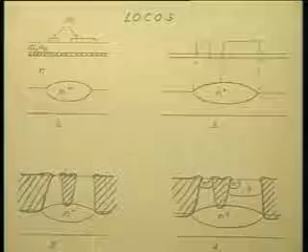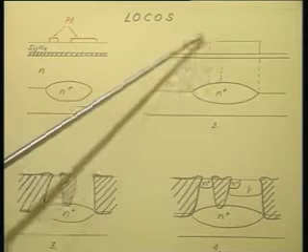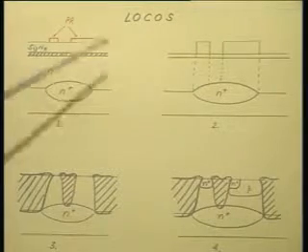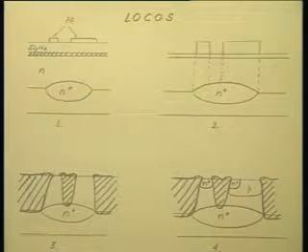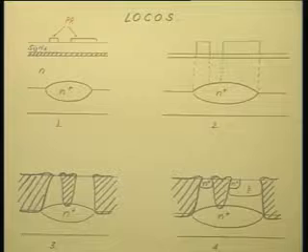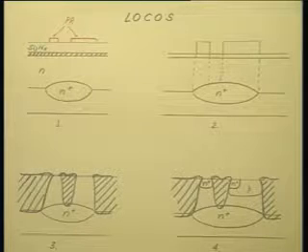Okay. So, if I simply use this silicon nitride as the mask and subject it to oxidation, then the regions where oxidation proceeds, I will have silicon dioxide coming on top of the surface. Again there will be loss of planarity. Do you understand the problem?